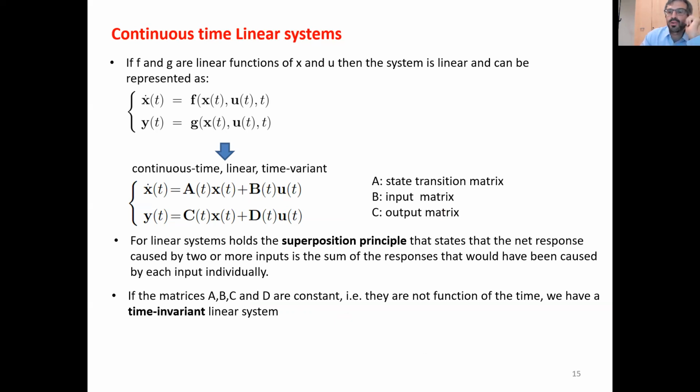It allows us to do frequency analysis of the system, which means we apply a sinusoid chirp signal, which is a sinusoid with variable frequency from 0 to whatever we want to see, and measure the output, and for each frequency we have a response.